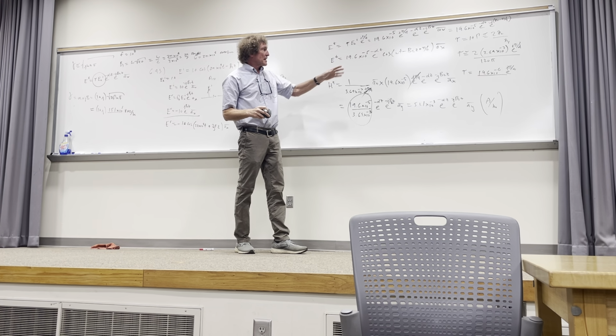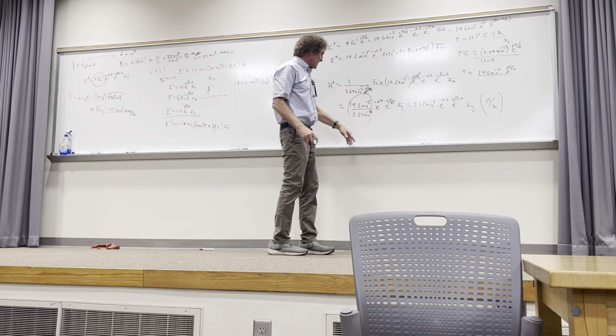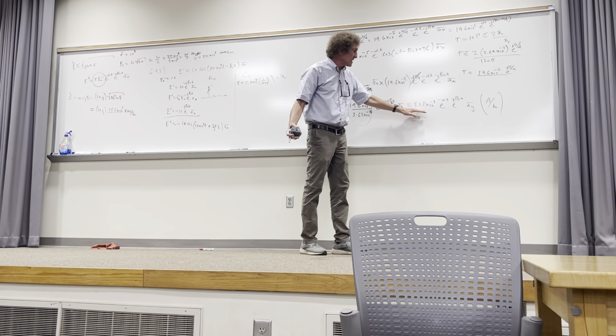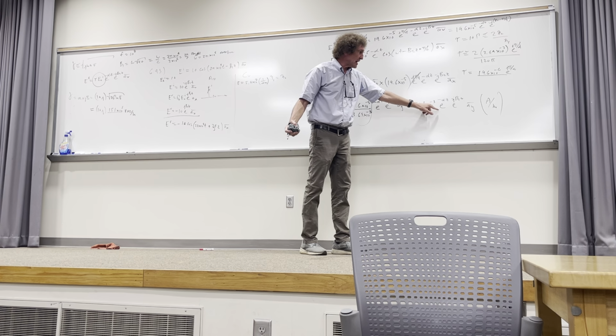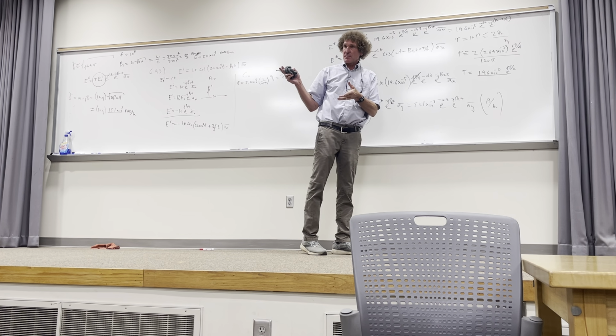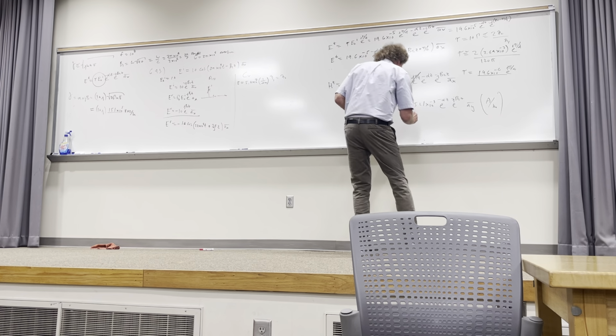And when I did that, now that would be the electric field that would be inside the conductor, and it would be out of phase with, I didn't put the time domain form, but if I wanted the time domain form of this one, do you all see it's going to be just 53.1 times 10 to the minus 3, e to the minus alpha z, and then it would just be cosine omega t minus beta 2z. Y'all see that? I'll write it down for you anyway.